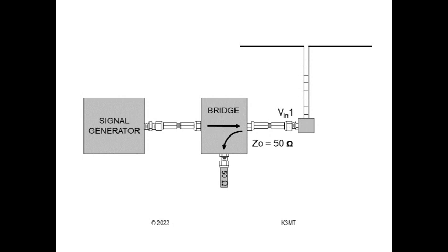By the way, the standing wave ratio, or SWR, involves the magnitude of S11. SWR is 1 plus magnitude of S11, over 1 minus magnitude of S11. There is a standing wave of both voltage and current, though many insist on calling this ratio VSWR. Please, it's simply SWR.